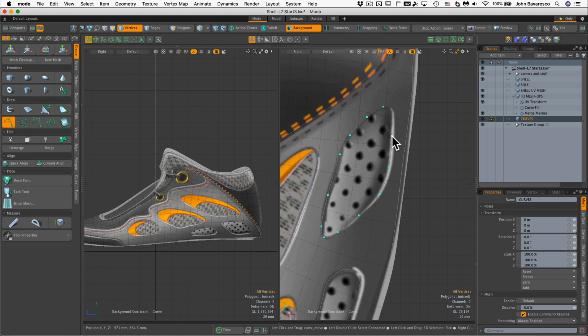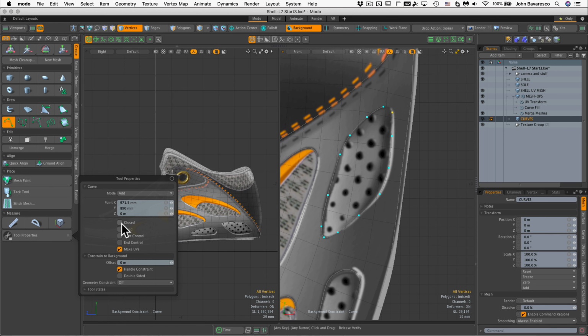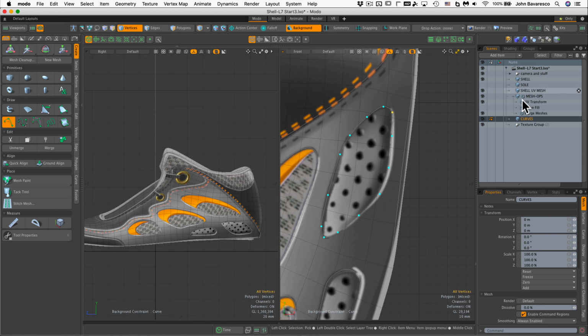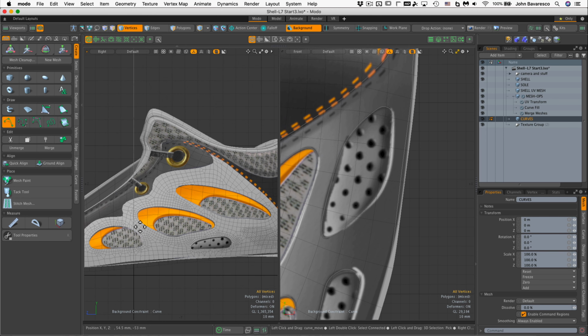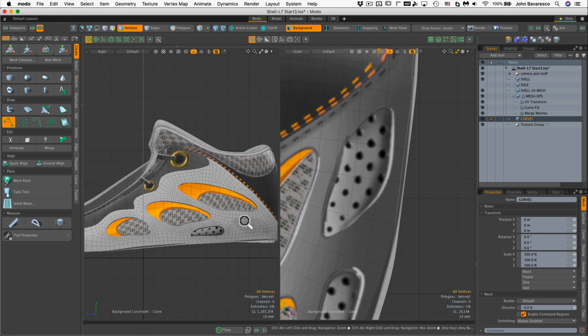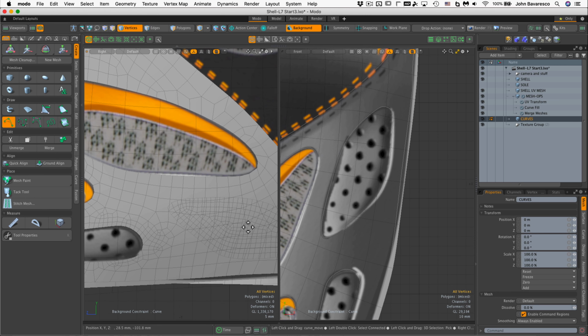Now let's say, for example, you kind of get spaced out like I often do, and you inadvertently made your curve in a counterclockwise direction. All right, and you go ahead and you turn on your fill, and lo and behold, you have cutouts where you have the curves made in a clockwise direction, but the counterclockwise curve you made here is filled.